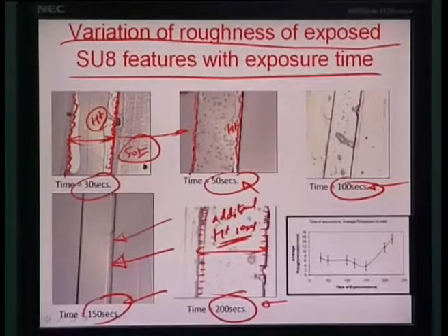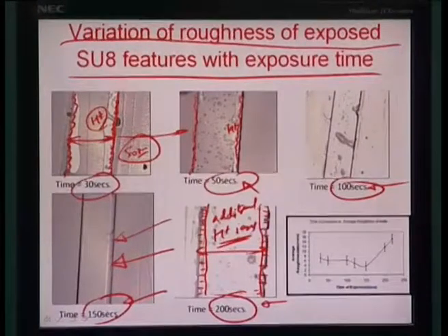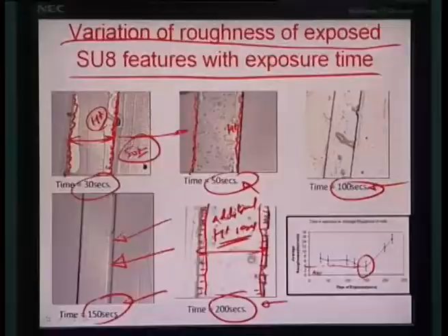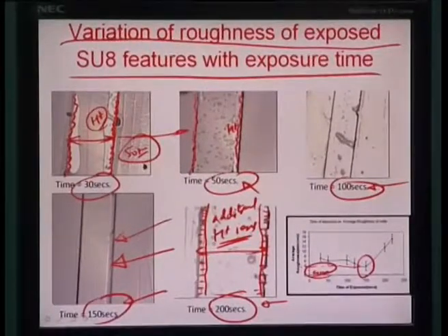That means this feature size effectively broadens out because of that. Maybe the 150 was just near about this, and this is broadened out by several more microns because of additional hydrogen ions which diffusively sneak past the edges of this particular configuration. So, if you look at the average scale, there is really an optimum best average roughness, which is about as low as about 4 microns or so. Beyond it, photolithography is sometimes not able to do its job properly, even if you are using a hard mask.